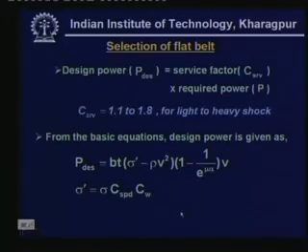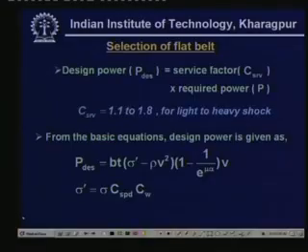Now, we come down to this particular concept of selection of flat belt. First of all, you are going to design the belt drives depending upon a design power. That is your objective: you ought to transmit a certain amount of power through the belt drive.